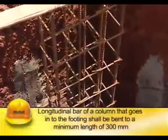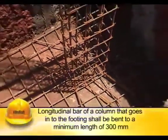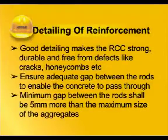The end of the longitudinal bar of a column that goes into the footing shall be bent to a minimum length of 300 mm to enable stability of the reinforcement cage till foundation is concreted. Good detailing makes the RCC strong, durable and free from defects like cracks, honeycombs, etc.